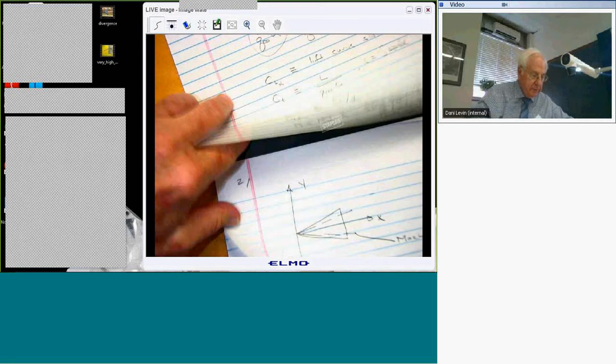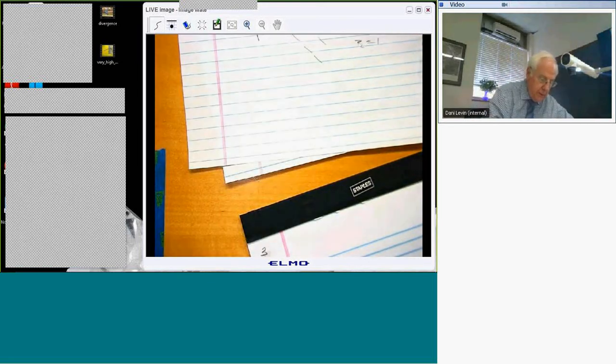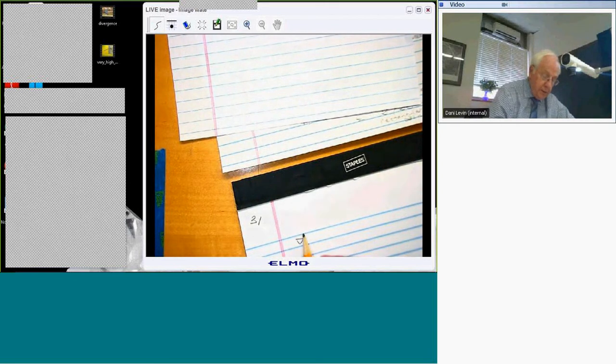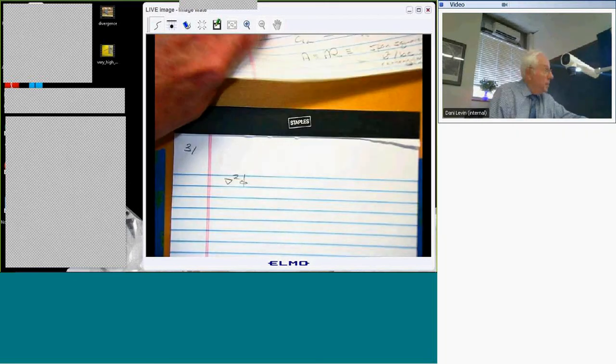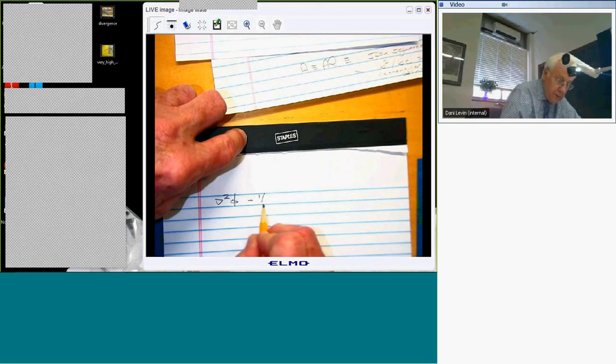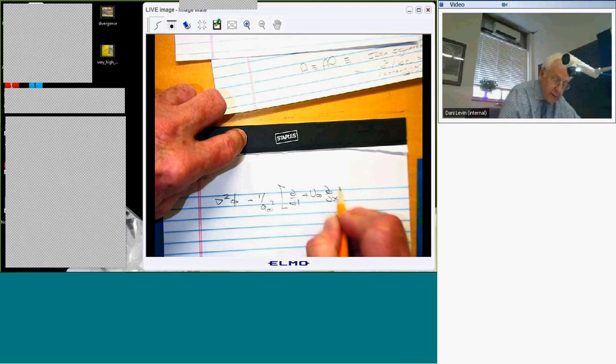Remember what we have in the classical theory. We have the Laplacian minus 1 over the speed of sound squared times d/dt plus U infinity d/dx, squared, operating on phi equals 0.